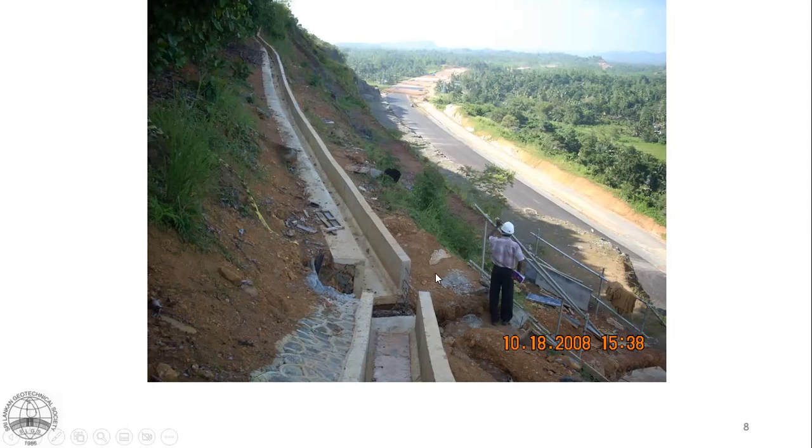With precast units, there is no proper connection between the existing ground and the drainage element, so there can be leakage through that. So in all these cases, for that to be effective, this should be constructed in situ. Then that binds with the existing soil profile without leaving any gaps